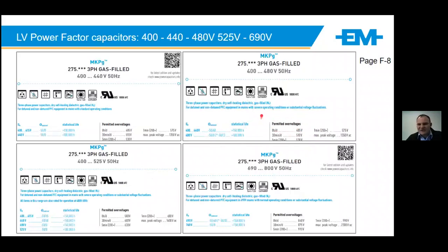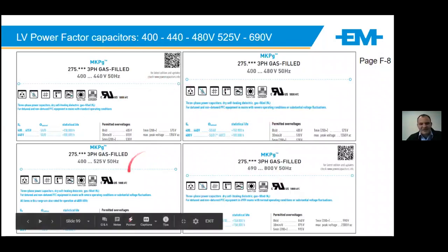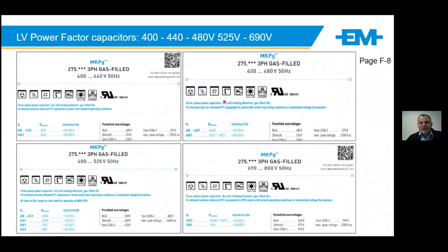We will say, at a percentage of the network voltage, disconnect that system. As much as any capacitor has its ratings, your protection resides inside your controller. And more often than not, customers do not make full use of all the protection systems that are allowed within these controllers.